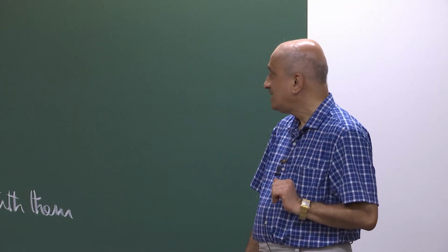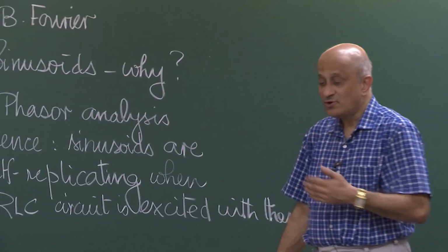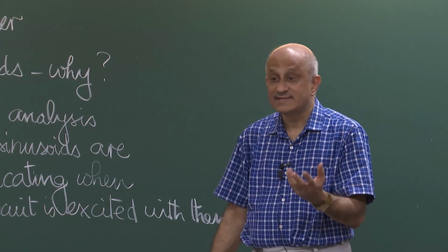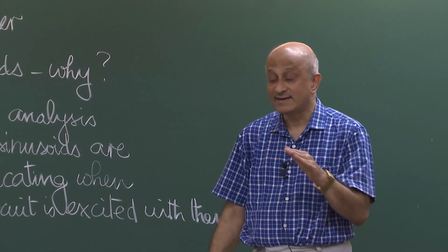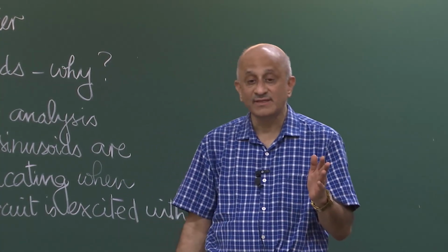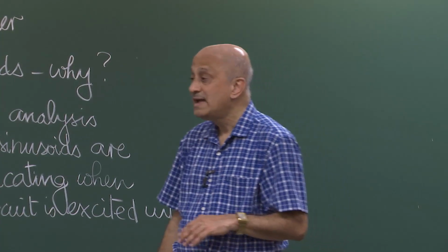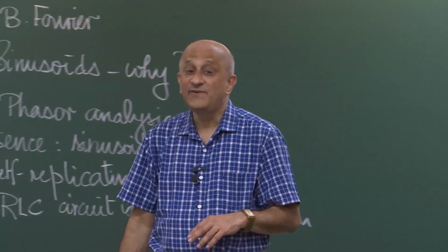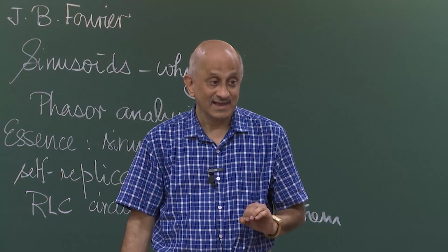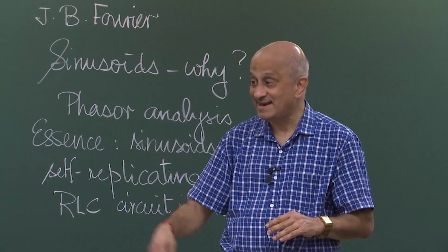Be that as it may, what are we trying to do in Fourier analysis? We are therefore trying to look at signals and systems, thinking of signals as a combination of sinusoids, or rather, that is the context of real signals. But if we are talking about signals in general, which could also include complex signals, then we will think of them as combinations of what are called phasors. Now, phasors are not quite the same as sinusoids. As I said, phasors are actually rotating complex numbers, right?